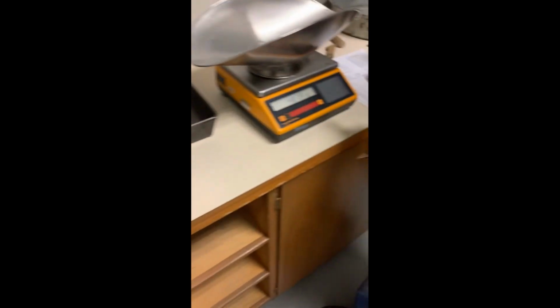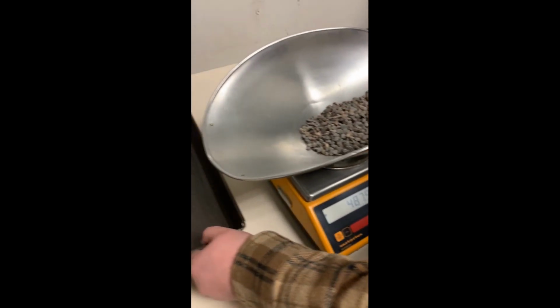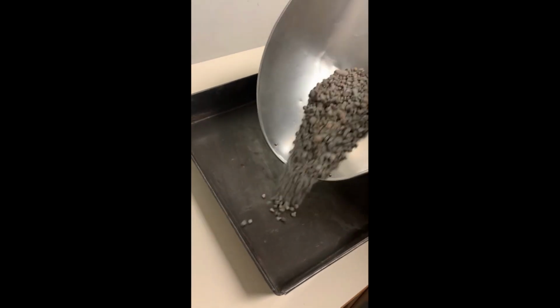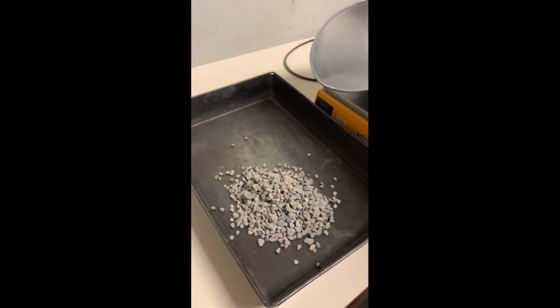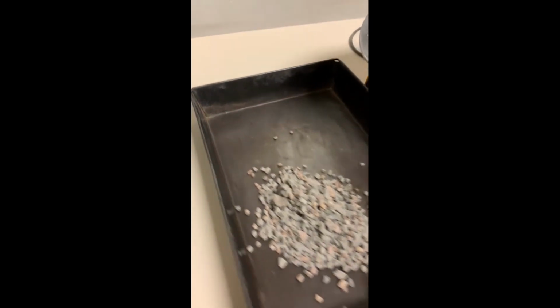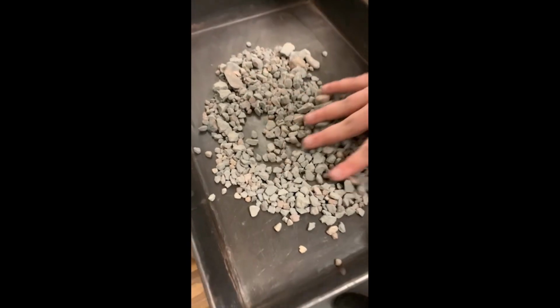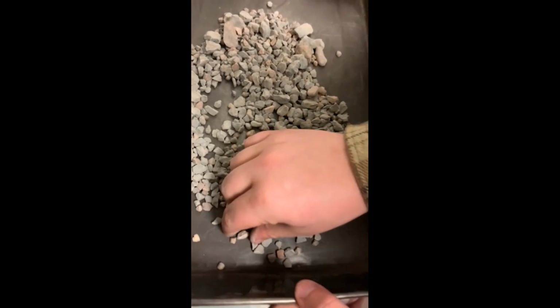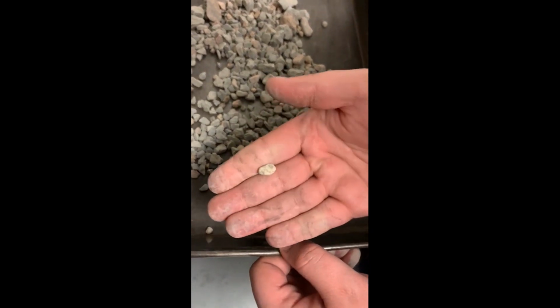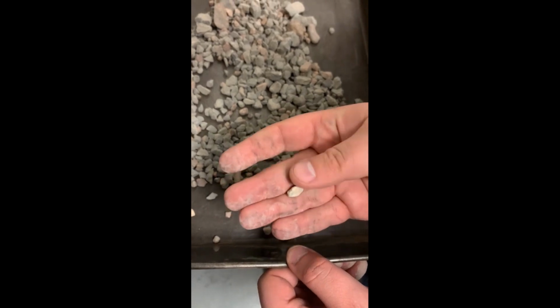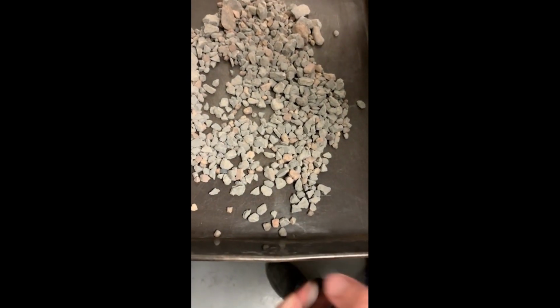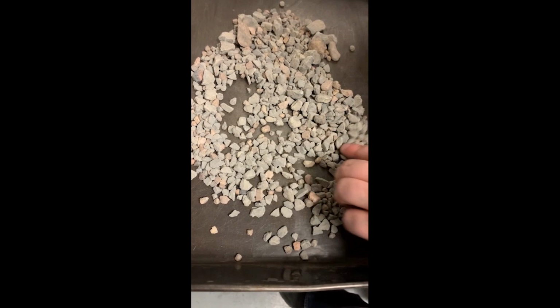Once the 3/4 sieve to the number 4 sieve's total weight has been collected, write the weight down and then pour it out into a pan and check for any aggregate that has no fractured face. Fractured face is any rock with a sharp edge to it, so we're looking for any that have round edges.